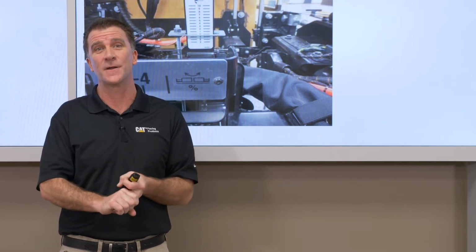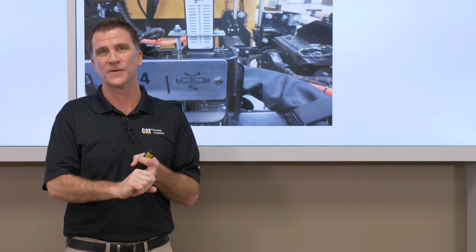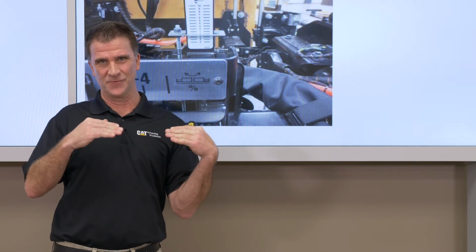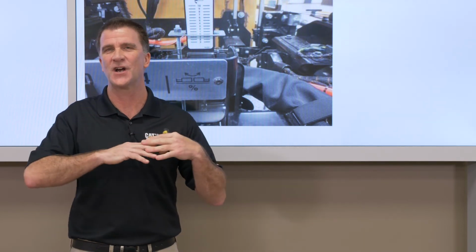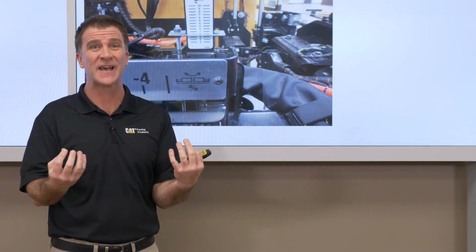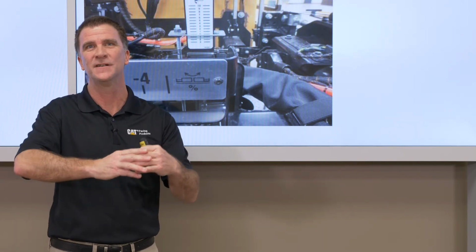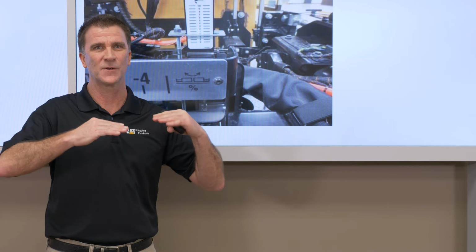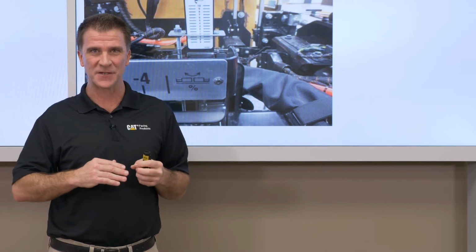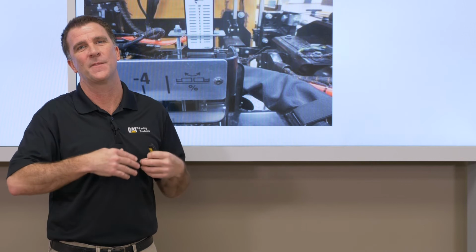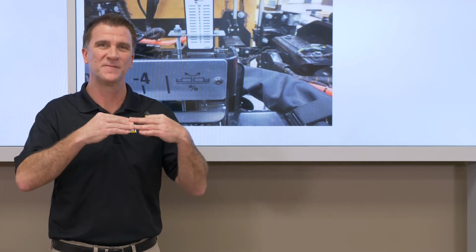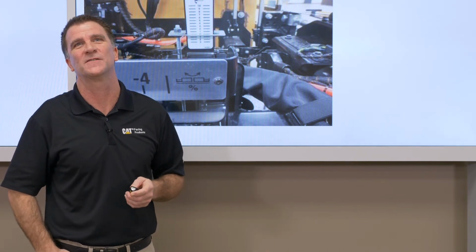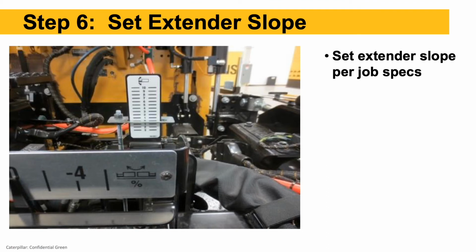One is it's very hard on the equipment, and more importantly, I guess, in terms of quality, is it's putting forces and tension on that screed. Remember that screed's free floating? It does its best job when no stress is acting on it, just floating on top of that mix. If we try making these types of adjustments while the screed's on the ground, again, we can put twist, torsion, tension on that screed, and then once we take off and we're on that loose mix that can move, that screed might torque into a different shape than we want it to. So again, all these are done off the ground.